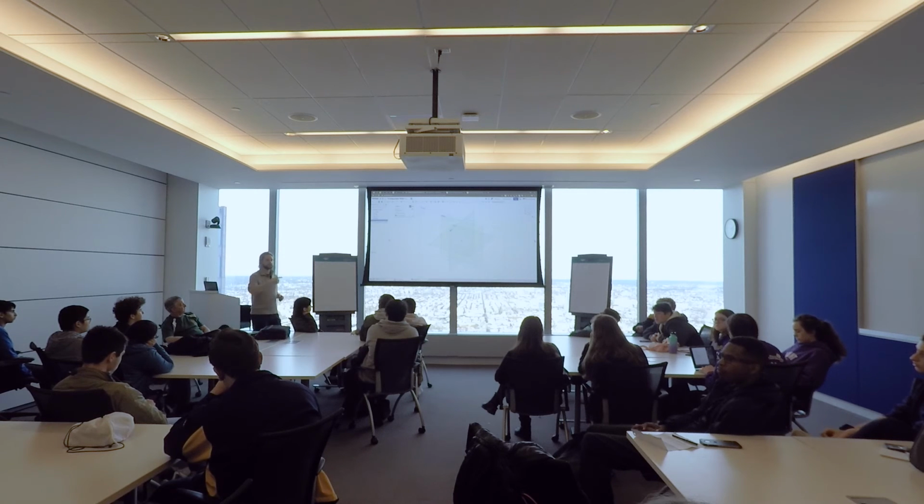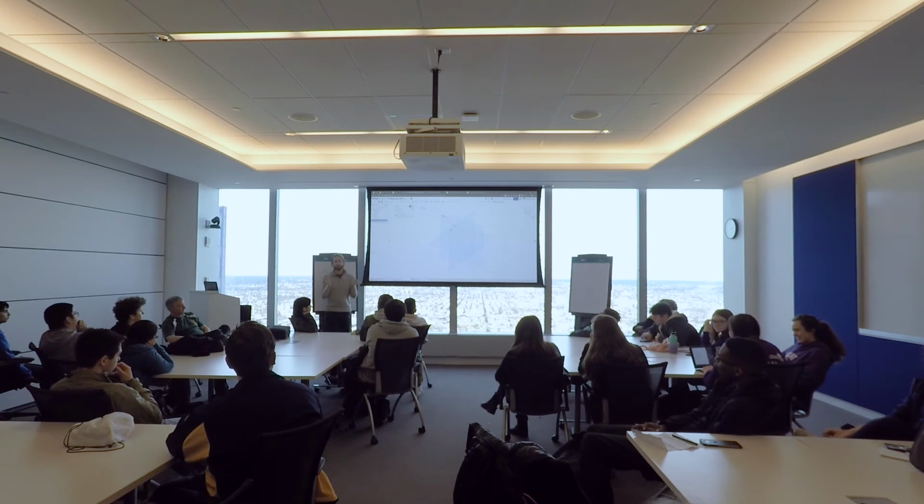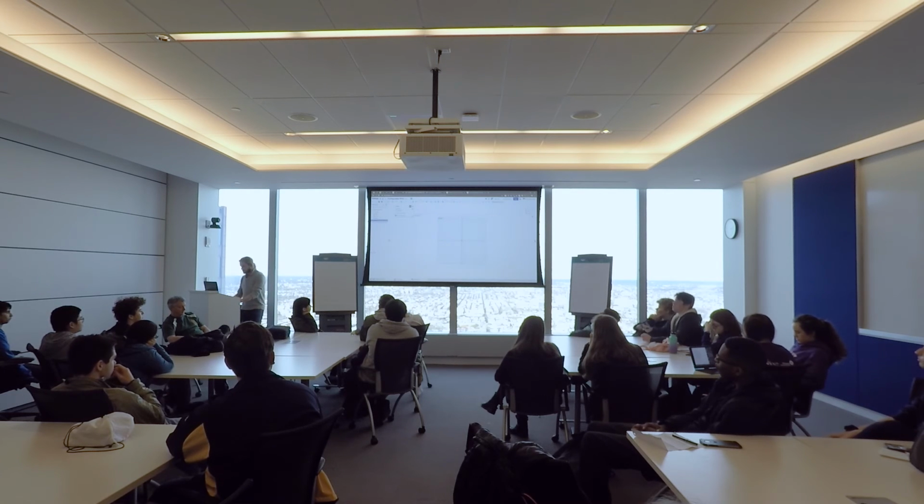I don't know exactly the lengths of pneumatic cylinders off the top of my head. You have to go to a site like Bimba, or go and grab a physical pneumatic cylinder that you have, measure its extended length and measure its retracted length, and then use that in your model. So you need some numbers before you dive into this, but I'll explain what's going on. So let's say I'll draw a really quick robot here.